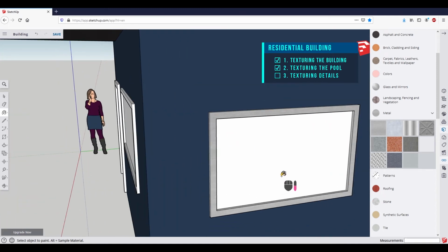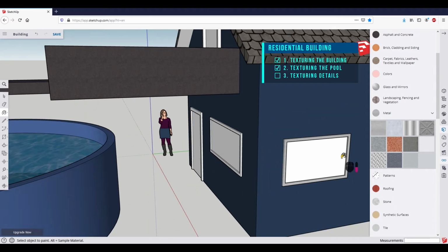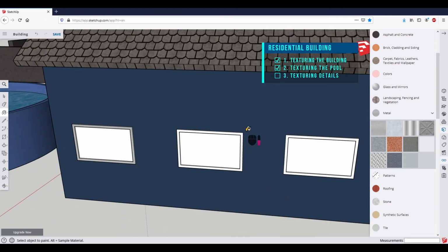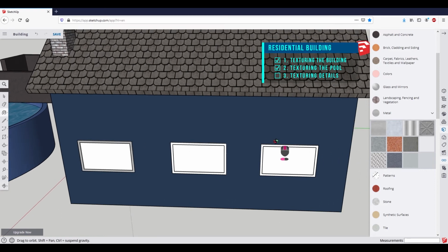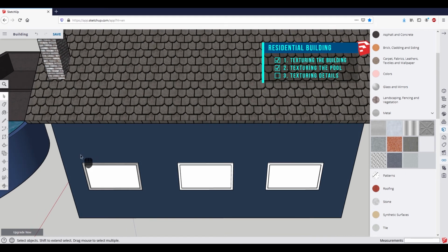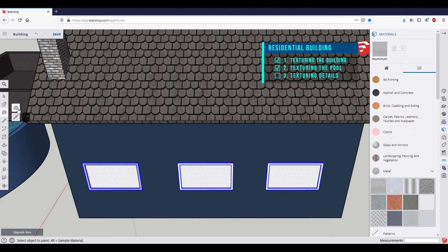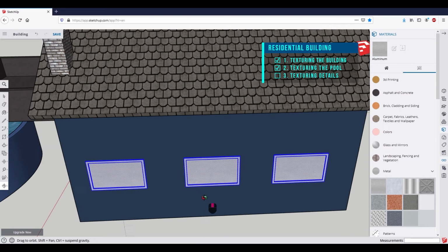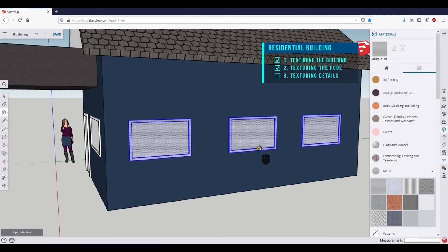Alternatively, we can angle the view from top to bottom so that no lines or faces are directly behind the frame. Now we can use the Select tool and drag a selection window from left to right around the window frame. Now select the Fill tool and click on the selection. This will also fill the face that is supposed to look like glass, but since we will use a glass texture for this face in the end, it doesn't matter.